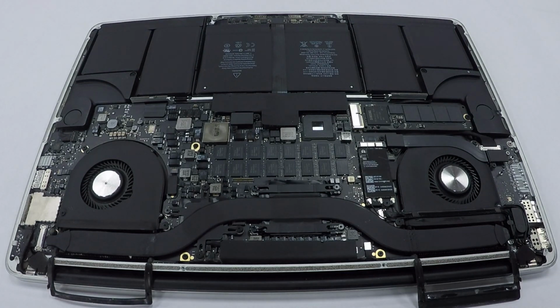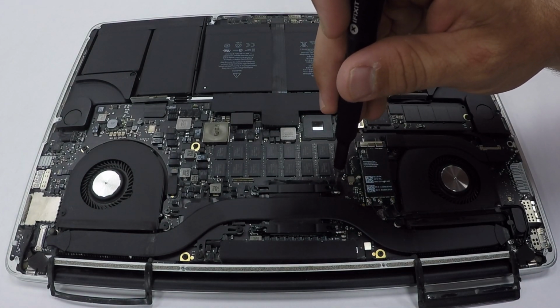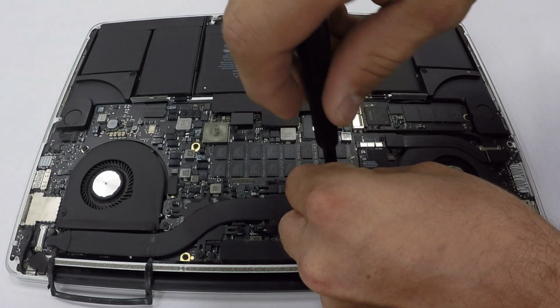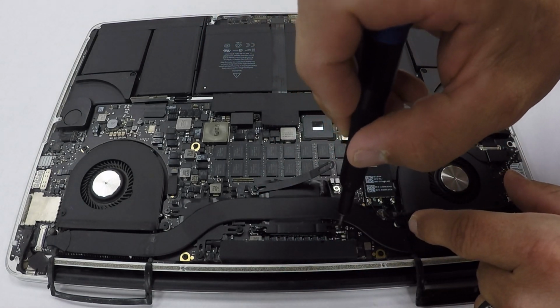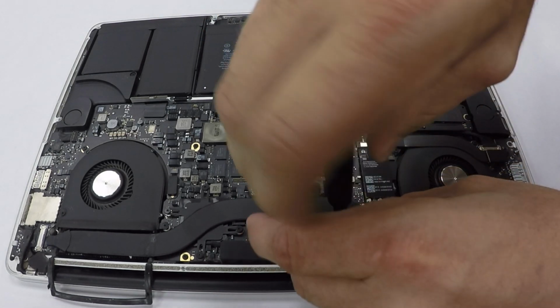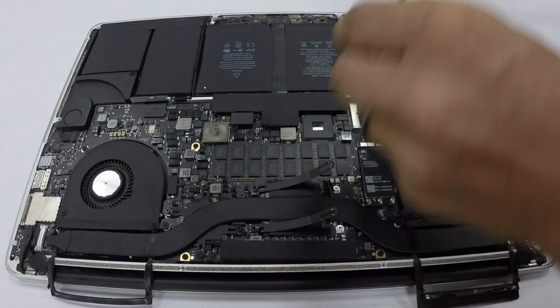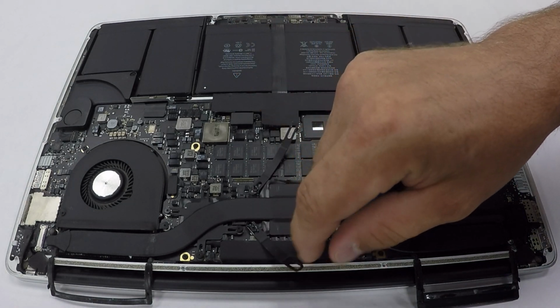I'm going to remove the two flaps, and then now I'm going to remove only two of the CPU block screws. Alright, now they're spring loaded, so be careful, have some pressure so you can catch the screw as it's rising. I'm going to remove the last screw at this time, and again, hold pressure. Alright, and then you're going to want to swing those arms out of the way so that when you remove it, it won't catch them.